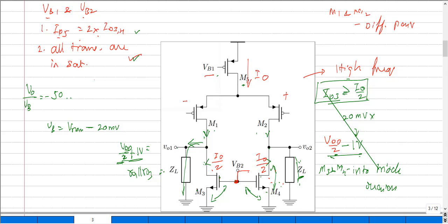So now this value has got raised, and how does it impact the entire circuit? Now this value would basically constrain the voltage drop across this M1 drain and source as well as the M5 drain and source. What happens is, either of these transistors would end up entering into triode region, or sometimes if the shift is so large, then both the transistors would end up entering into triode. So that is what would happen when the common mode voltage is shooted up.